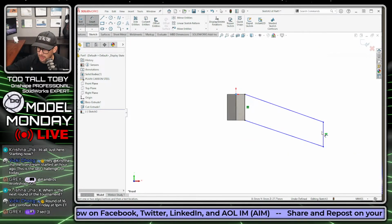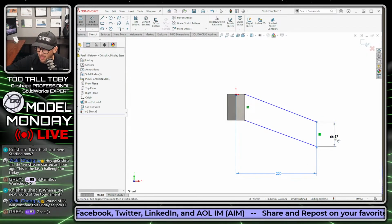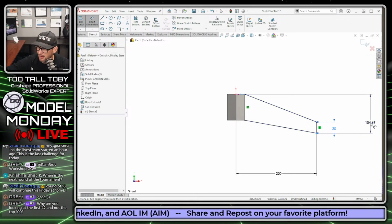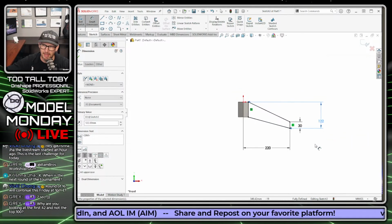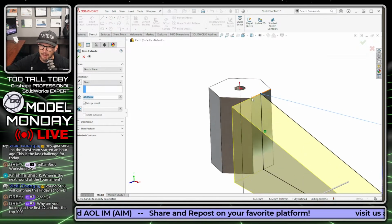So the dimension from the origin to this outer edge here is 220. The length of that outer edge there is 30 millimeters. The depth from the top of the part down to the bottom point there is 122, and boom, that sketch is nice and fully constrained. S key, extrude, and that's going to come up to a point here.